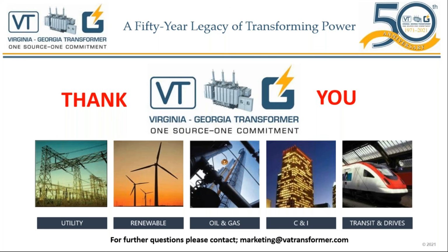What about online PD? How frequently is it required? I'll take that. This is Hakan. The online PD depends on the usage of the transformer, of course. If it were my transformer, I would try to do that maybe every 3 years. That will be a good frequency to do it. And of course, another answer is after an event, that will be recommended as well.